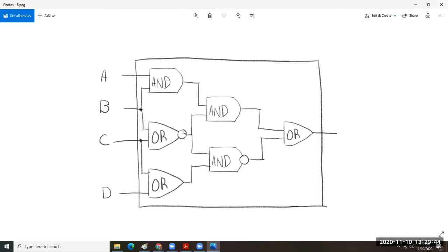Except that that's a NOR and that's a NAND, I think. Pretty sure, because that's a NOT. So that would be a NOR and a NAND. That would be the only constructive criticism I would offer for this designer: if you put OR and then you put the dot, people are supposed to know better. But if you want to be consistent with the symbol and the label, you'd probably want to say NOR and NAND. But other than that,